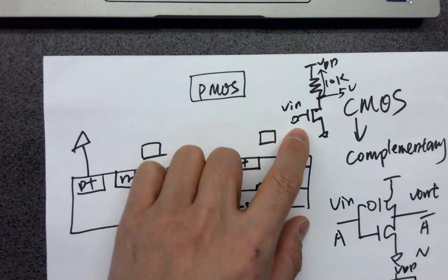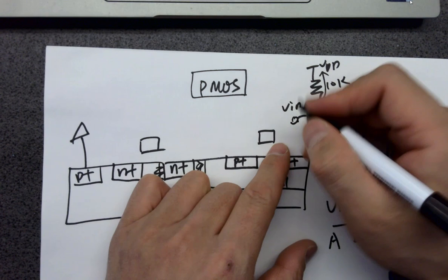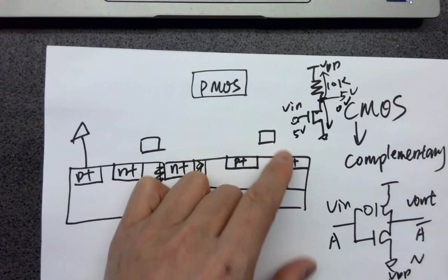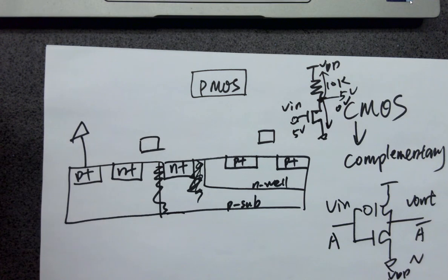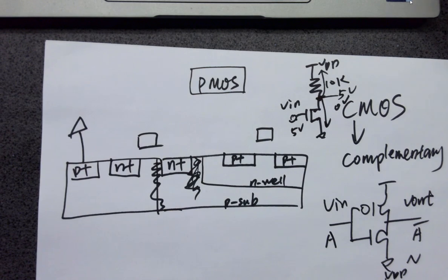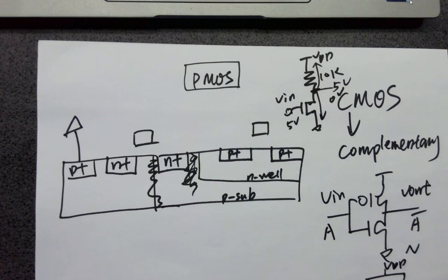It's inverting. 0 volts input gives a 5 volts output. And if you have 5 volts input, it turns on, so the output is pulled to ground, and I'm getting 0 volts. It also works, but what's the problem? Come on, resistors, like N-well resistors, you're serious? You can probably only integrate about 1,000 NMOS transistors and resistors on the chip, taking a huge area.